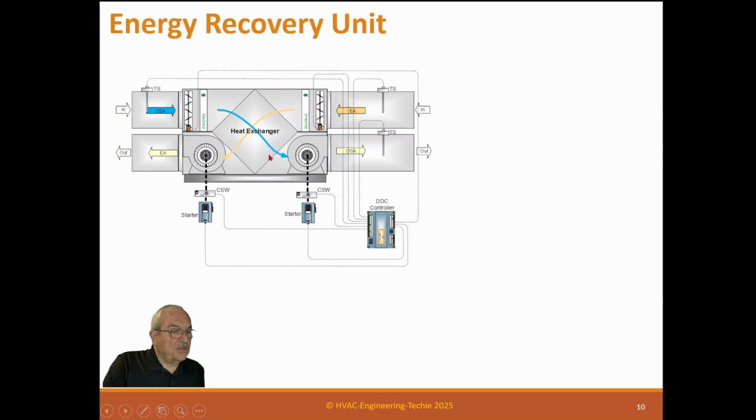Now, this heat exchanger does not allow the outside air stream to mix with the exhaust stream. In a heat wheel it will, and the reason is because it has bypass. A certain amount of air bypasses the wheel because it's only sealed with brushes. So a heat wheel cannot be used in any circumstance where the exhaust air has contaminated air in it, like from a restroom or from the soiled linen or lab or something like that. So then you would need to use an exact heat exchanger that separates the streams.